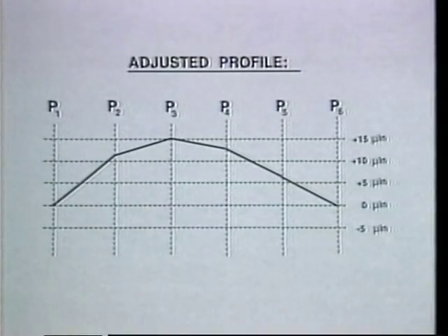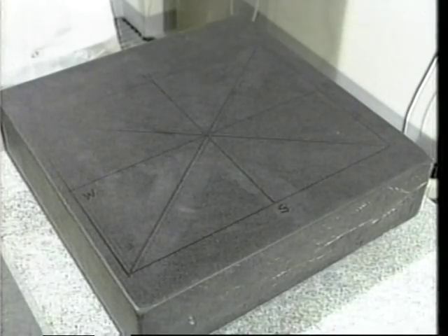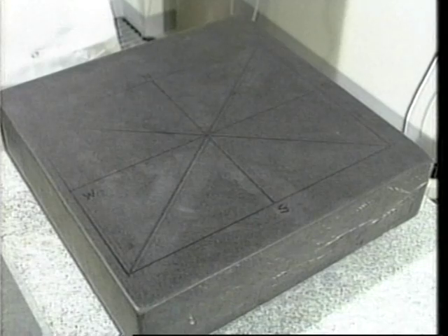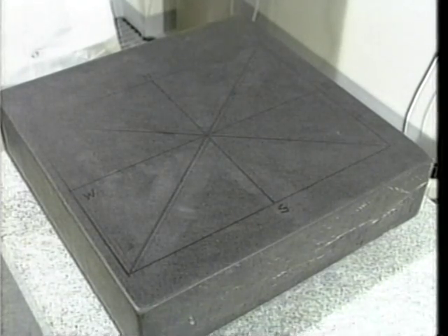The data is now plotted to show the deviation of the surface along the measurement path. This was the procedure for mapping a line along a surface. This procedure is often performed on carriageways to determine the amount of pitch along the axis of the carriage travel. To map an area of a surface, 8 measurement paths are constructed to form the Union Jack pattern.